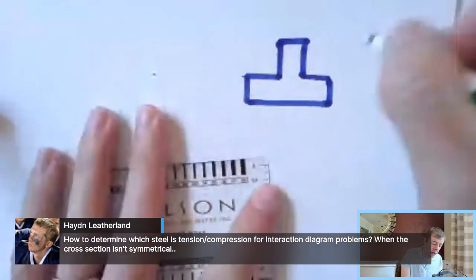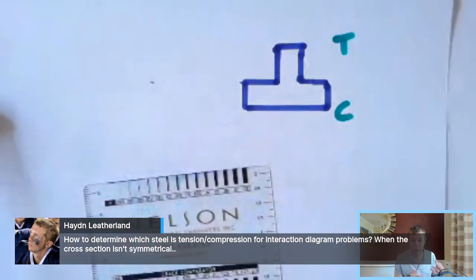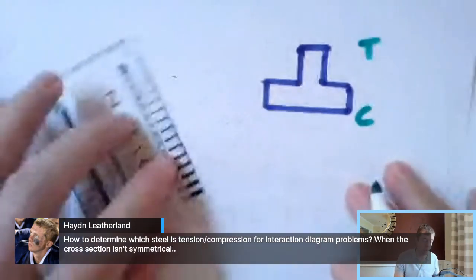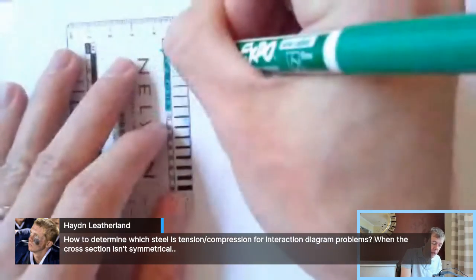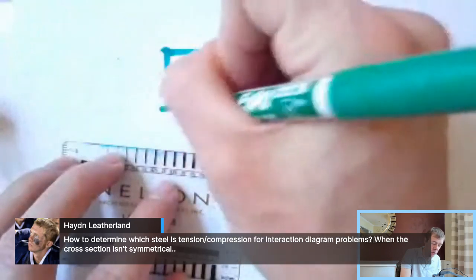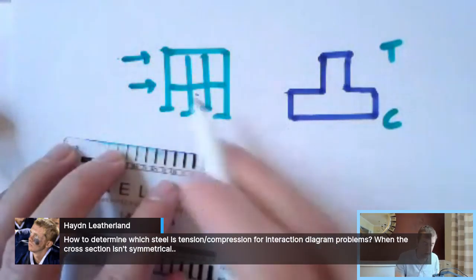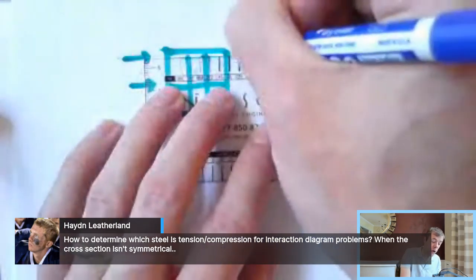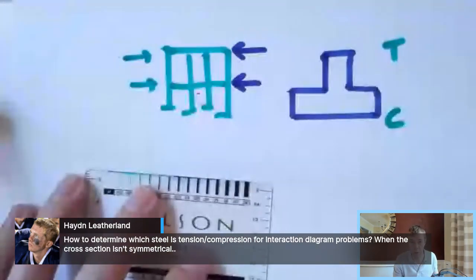And we have, let's just say, compression on one side and tension on the other side, something like that. And you'd say, Hayden's question, how do you know? Well, Hayden, when you do your lateral loads on a building, that's the ones where you draw like a frame, and you think about the load, the wind blowing, or if you do an earthquake or whatever else. You usually think of the wind load going in one direction, and that might cause compression on one face and tension on the other. And then guess what? The wind doesn't just blow in one direction. The wind blows in multiple different directions, and earthquakes happen in multiple different directions.